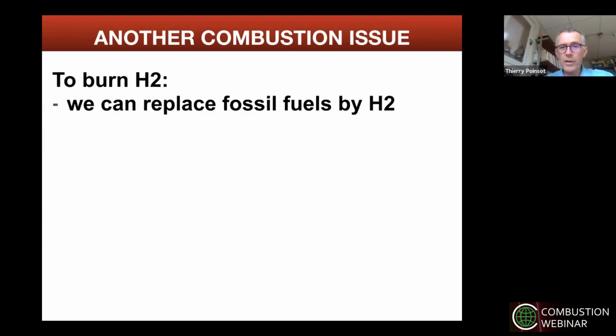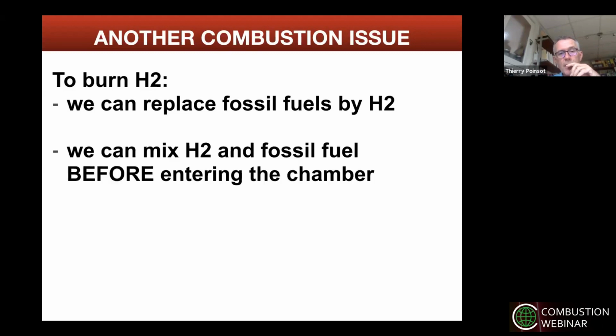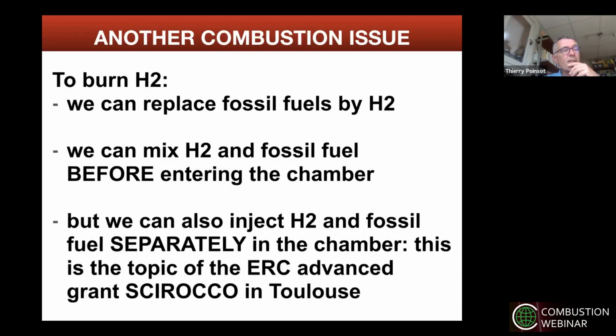Now, another question related to hydrogen. Of course, if you have hydrogen, you can say, let me throw out my fossil fuel and replace it completely by hydrogen. But you could also mix H2 and, for example, methane before entering the chamber. That's what we do in the drop-in methods, where we add hydrogen into methane lines and we feed it into all kinds of burners. Another method is that you could also inject H2 and your fossil fuel together in the chamber, but not at the same place.